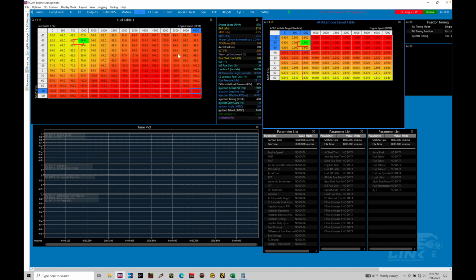So let's assume at idle here, I've dialed my values in here to roughly 63, 66%. Previously it was at 1.0 lambda. And we're taking a look at our actual pulse width here. So it's 1.87. If I command a lower number here, that's going to command a richer target lambda mixture, what we'll find is that this pulse width will increase. It'll do that specific to the exact amount of pulse width that has to happen, the exact amount of fuel flow that has to happen in this math modeled system in order to hit this desired target lambda.